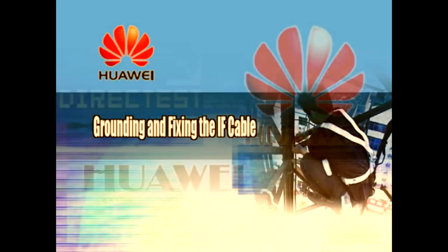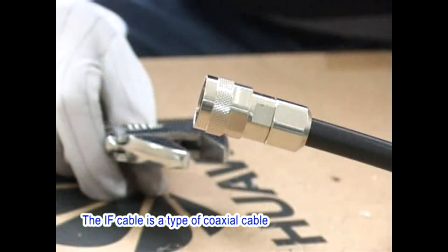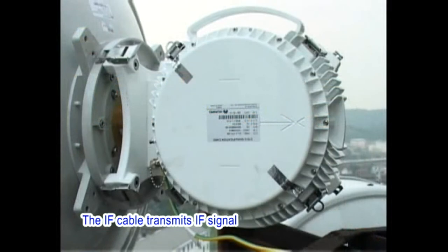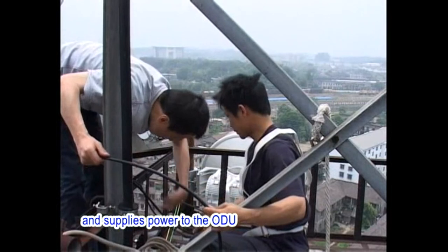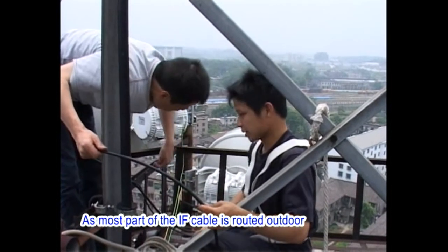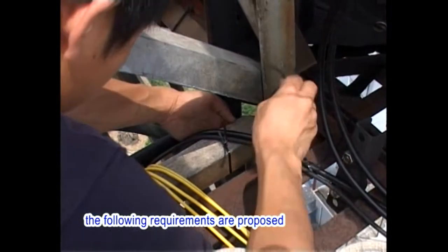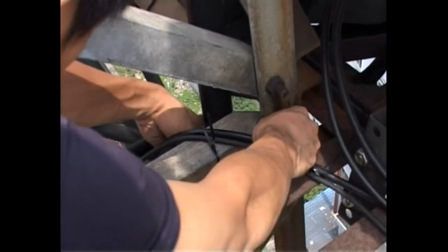4. Grounding and fixing the IF cable. The IF cable is a type of coaxial cable used to connect the IDU and the ODU. The IF cable transmits IF signal and supplies power to the ODU. As most parts of the IF cable are routed outdoors, the environment can greatly affect the performance of the IF cable. Therefore, the following requirements are proposed for the grounding and fixing of the IF cable.